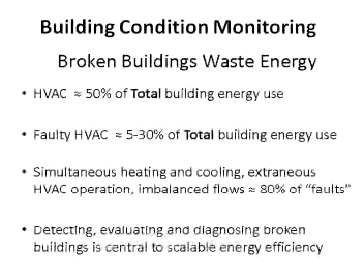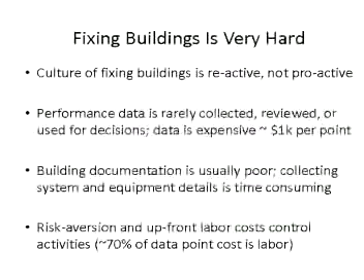Finally, and I'm just going to briefly talk about this, we have another student looking at how do we monitor commercial buildings. And in this case, what he found out is in many cases, simply the building is operated incorrectly. For example, he did one building at MIT and found out that for the air handler, which delivers the conditioned air to the space, the heating and cooling systems were both operating, so they were fighting each other, and substantially increasing the energy. Let me get beyond that.